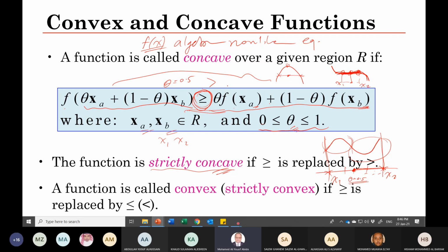In these equations, you are solving them using the Newton-Raphson method or the Gauss-Seidel method. You take the derivative, the partial derivative of P and Q with respect to theta, V, and so on, and you put them equal to 0. So you can get the Jacobian matrix. And so you are searching for the equilibrium point.